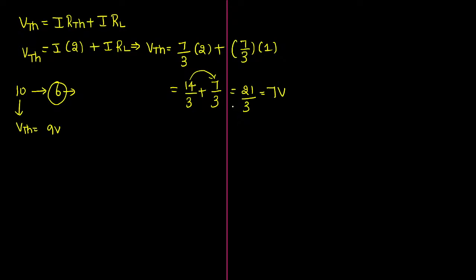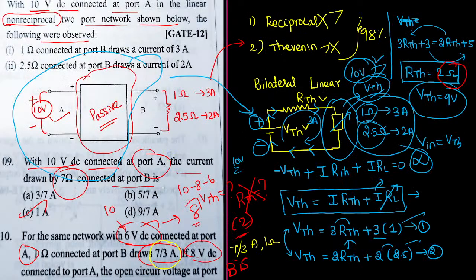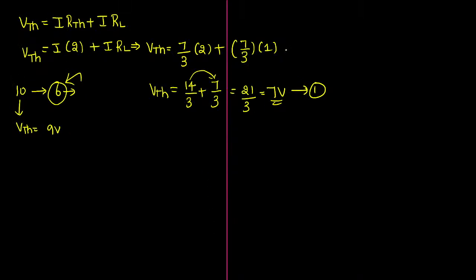That is very simple now. So the expected Thevenin voltage when we connect the new voltage source at the input port will be 7 volts. That is how we apply the basics. Okay, sir. Let me treat this one as equation number 1. Again, what they did is, one more time they connect an 8 volt DC source at port A. Then they ask what is the expected open circuit voltage. In the same way, take the same original circuit now.